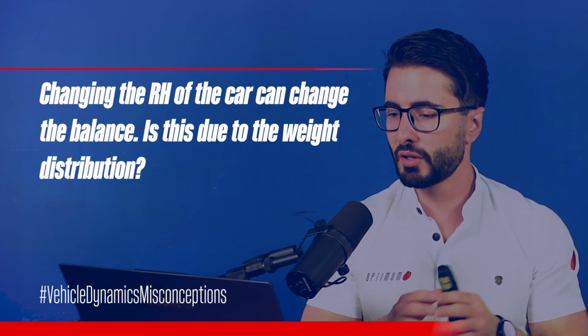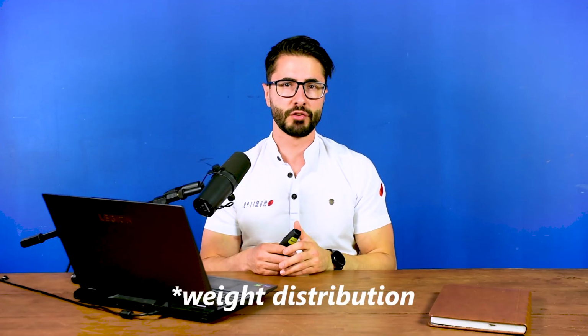Changing the ride height of the car can change the balance. Is this due to the weight distribution? No, it is not. When you change ride heights on a race car, typically you are operating within a window of 10 millimeters. This will not shift the weight transfer, at least not in a significant way. If you are playing with just a couple of millimeters, this is not enough for you to shift the CG position forward or rearward, meaning that you can do whatever ride height adjustments with the car, the shift in the weight distribution that you see on the scales will be really, really minor.